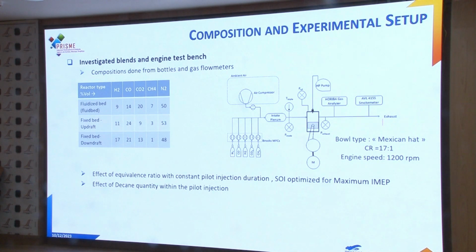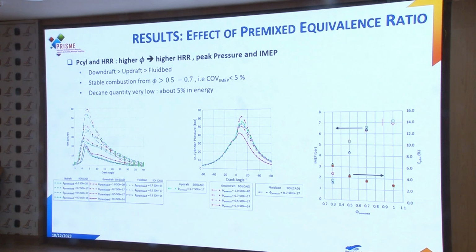So first, the effect of the equivalence ratio of the premix charge with a constant pilot fuel injection, using an optimized start of injection to get the maximum IMEP. And we also studied the effect of the decane quantity for the pilot injection, so adding more and more decane to see how we can get different performances. So these are the first results. It is the effect of the premix equivalence ratio, so the equivalence ratio of the syngas air mixture.